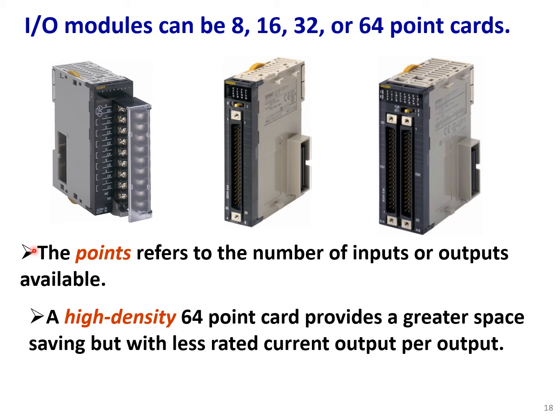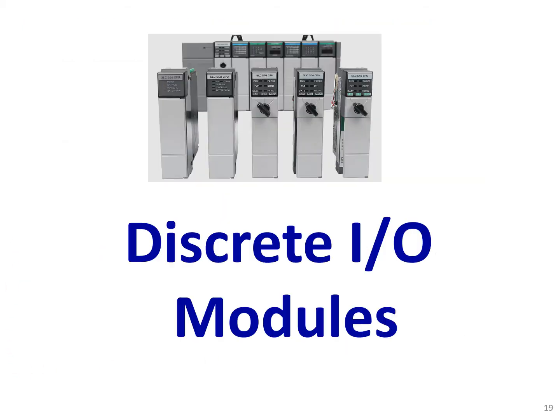We should have an appropriate number of points for our specific application. If the number of inputs is 8, we should avoid having a card with 32 or 64 points, for the cost aspect. Plus, as you could see here, for the rated current and the space.